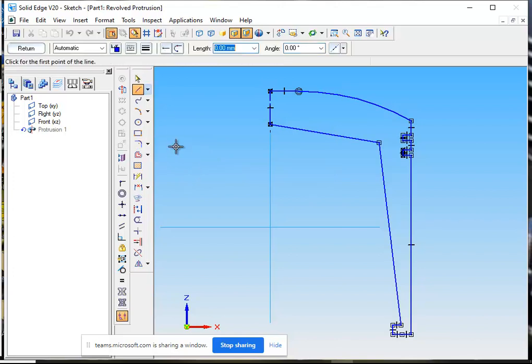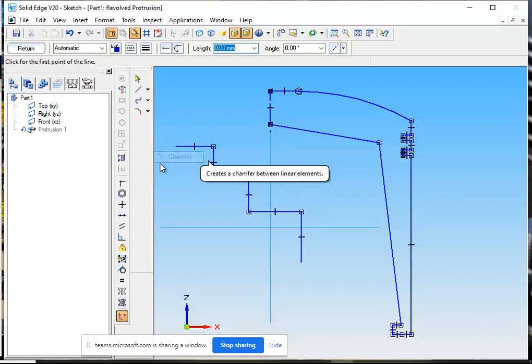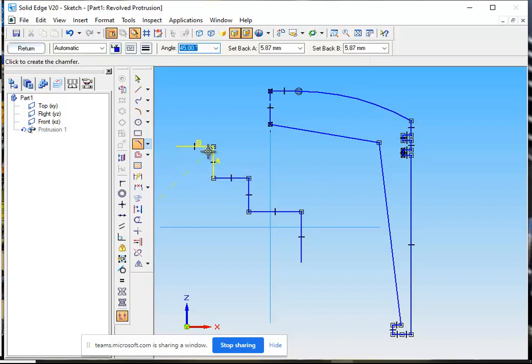For example, I will draw a line over here. I have drawn different edges over here. This is the outer edge, this is the internal edge, outer edge, internal edge. Now let's see how the chamfer command works. Chamfer command, I click on the edge, drag it, and you see the edge is replaced with a straight line. In the case of fillet command, our sharp edge is replaced with the arc. Here we replace the edge with the straight edge instead of an arc. You can see that we can remove the edge and we can make the edge with the elbow sharp edge. Now we delete this one.